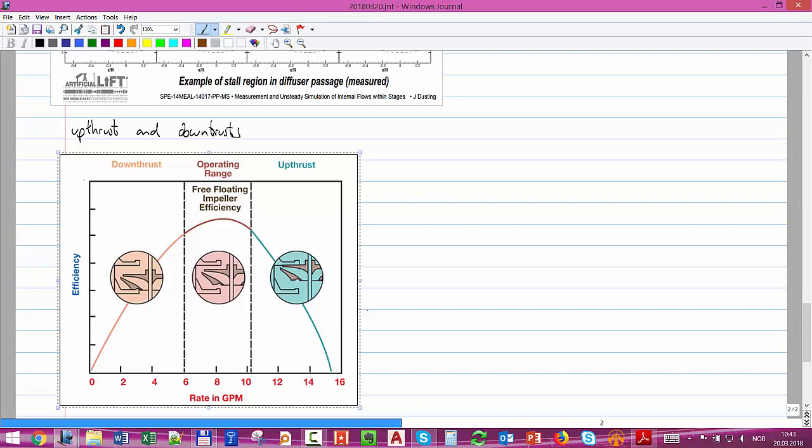Usually if you have this floating type pump, the impeller is not fixed to the axis. It has the ability to move together with the axis. We will see now, it has something that allows it, when the axis rotates, to rotate, but it can go up and down.